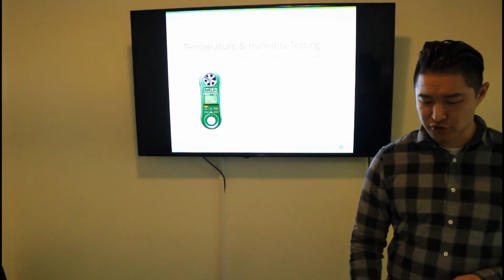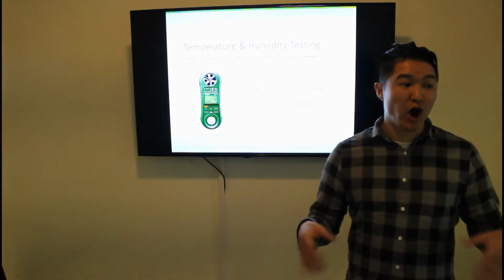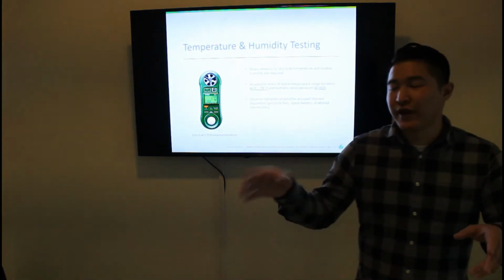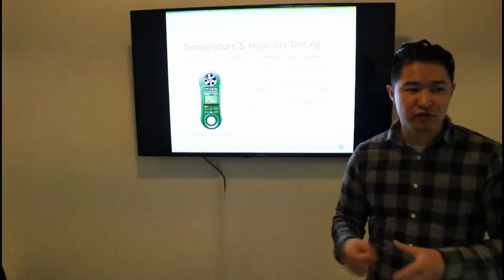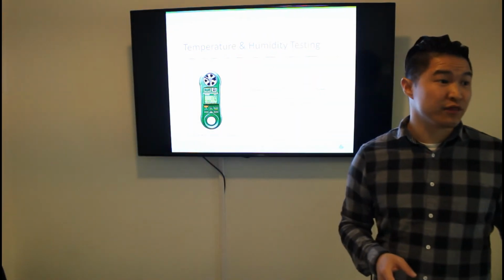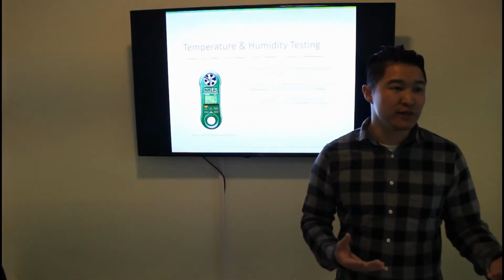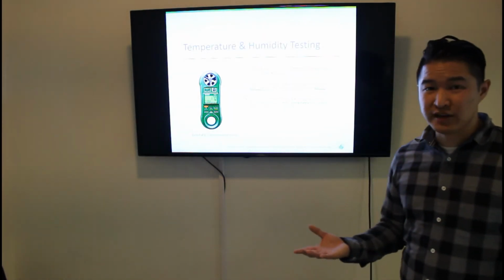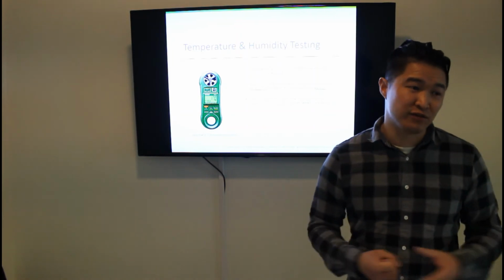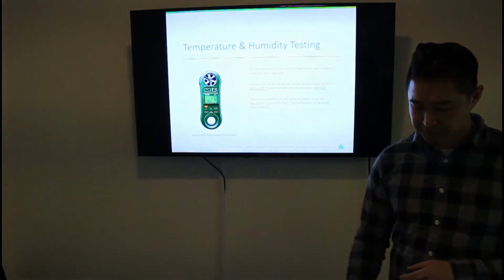It's also important to note if you see any occupants using things like personal fans, space heaters, or if they've significantly altered their thermostats. These are definitely things you want to note because it's a sign or indication that their current room conditions are probably not being satisfied. So it's definitely something you want to look at.